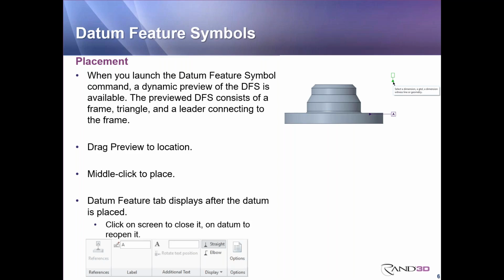When you click the wheel button during the preview of the datum feature symbol, that particular feature aborts, placement and procedure, everything is terminated along with the command.